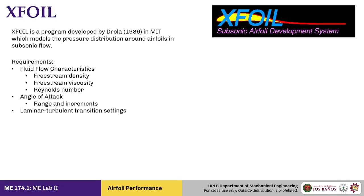Now, another thing to specify is the transition settings for laminar and turbulent flow. This occurs over the airfoil, but you have two options in Xfoil. You can leave the program to actually guess where the transition happens, or you can just straight up say the transition will happen at this point. When you say the program is free to solve for the transition point, it will ask you for this particular quantity, ncrit.